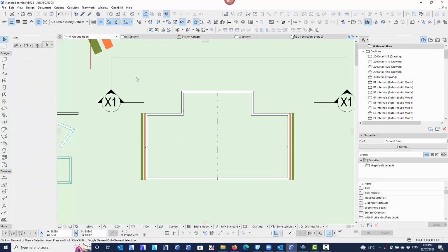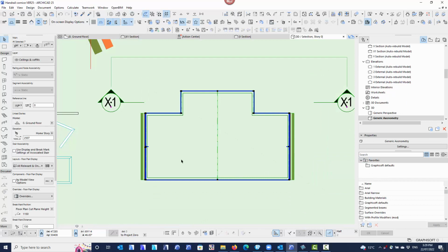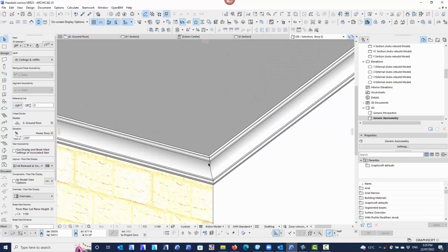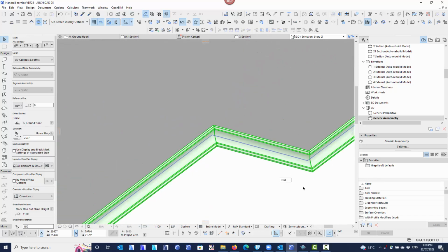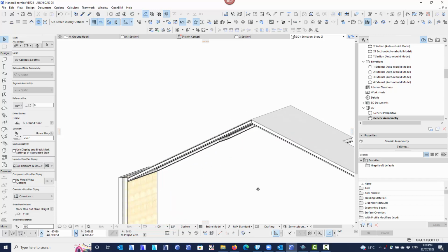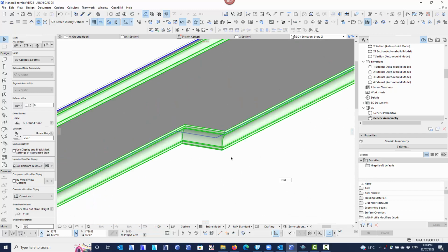So with a little bit of messing around, let's grab this and look at it in 3D. You've now got a cornice. All the corners will mitre automatically. Brilliant. Doesn't matter what angle they are at, they will mitre. So long as you match the rake and the roll to the ceiling angle, or the rake is automatic because you just drag the nodes, but change the roll angle to match the ceiling angle. So long as that matches exactly, you'll get a perfect mitre in all the corners.